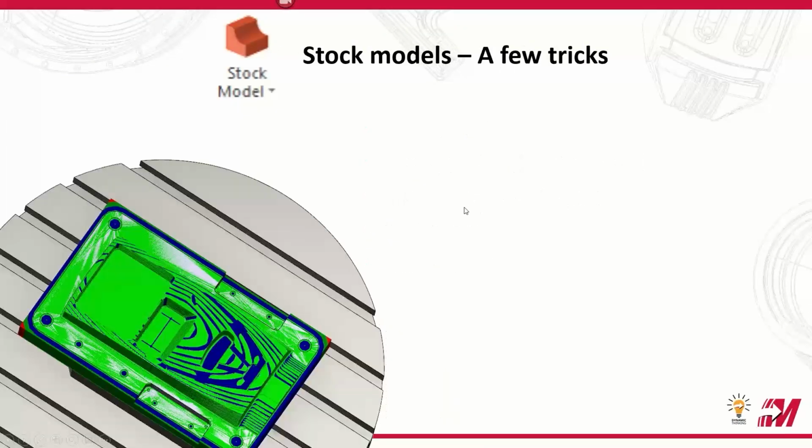So now I want to touch on a few tricks that you can use to enhance the functionality of stock models, or a couple little things that will make life easier when you're using stock models inside of Mastercam. One of those big things is tolerancing. This is something that people all too often look over, and they just stick with the default tolerances.